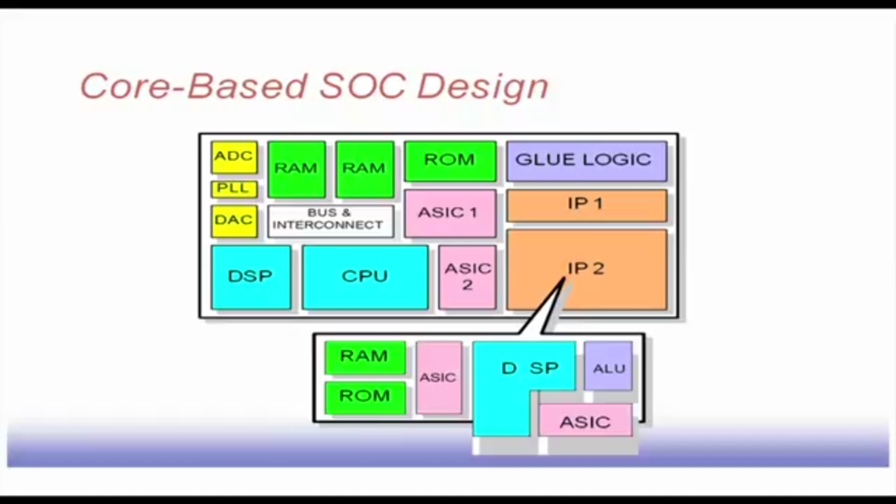But none of them can give me the design, because that is what they are doing. What they give is nothing but a layout level description of the whole structure. And that layout level description, if fabricated properly, will give me the system. So, if I have the layout level descriptions of, say, CPU, DSP, RAM, etc., and synthesize the whole thing together, then all the off chip connections between, say, CPU and RAM, become on chip connections. As a result, the speed and the system performance will be better.